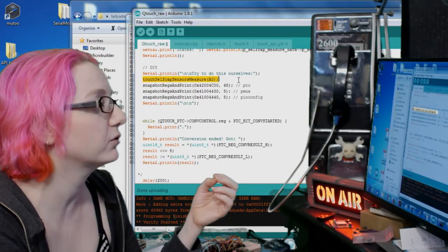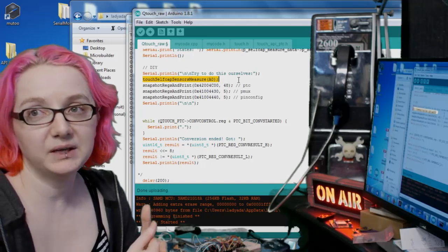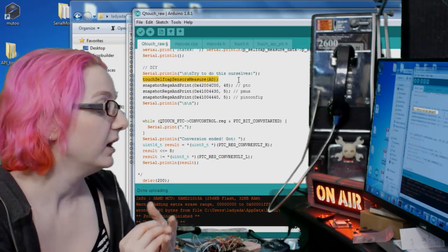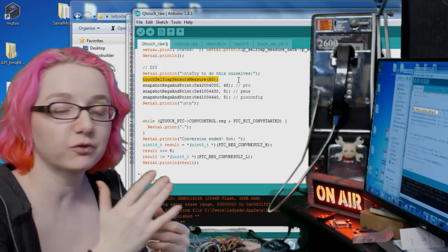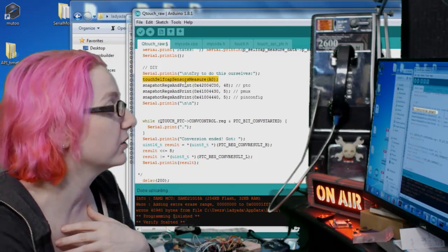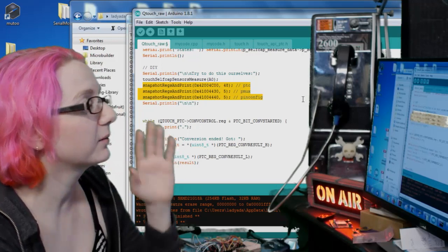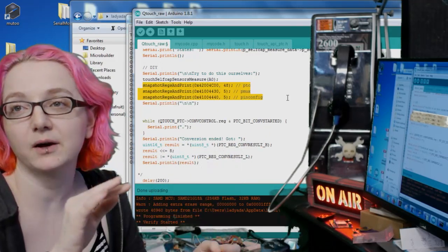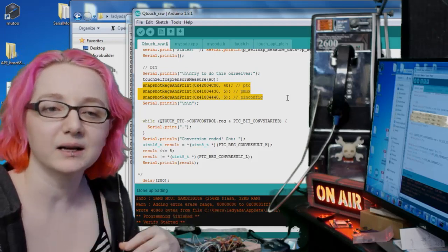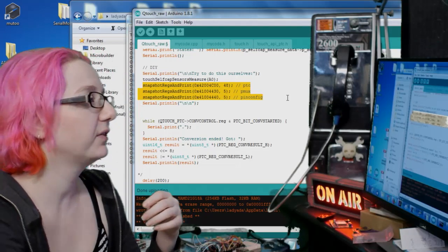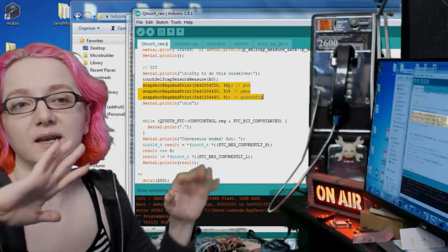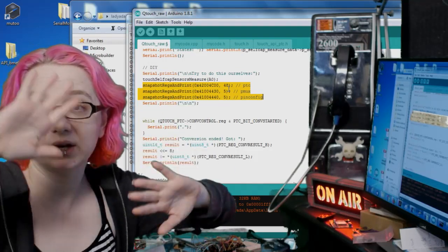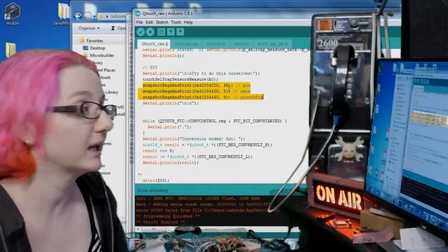Touch self-cap measure, sensors measure, enables the PTC, configures that pin to be the peripheral for touch, and then actually starts the conversion by setting a bit in a register. And then just for my sanity, I have these functions that snapshot the registers and print them out. It's like a printf debug. It just takes a snapshot of these register locations because then I can compare what my registers are to what the library sets them to, and I can sort of check, do mine line up?